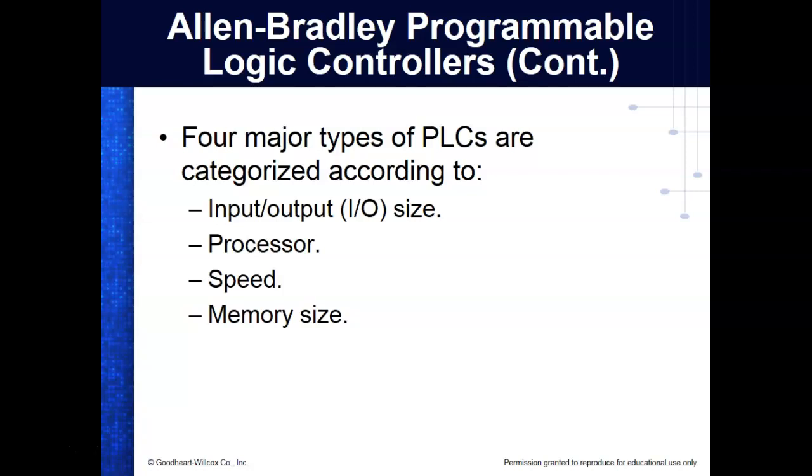So everybody okay? You've seen a fixed PLC and a modular PLC? With a fixed PLC, you can't add anything to it. You're stuck with the number of inputs you got, the number of outputs you got, and the type of output.